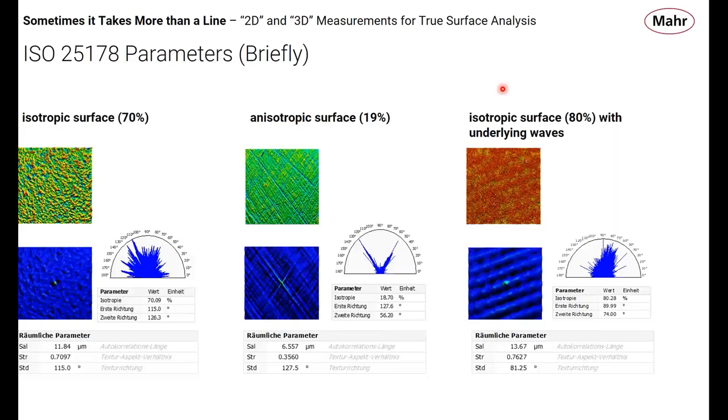And the reason I say that is, first of all, our isotropy is very, very high, but the two things that key me in there are our texture aspect ratio, which is actually quite high. It's higher than the surface over here that I called the isotropic surface, meaning that the isotropy signal is even lower. So the waviness isn't really having much effect on the isotropy at all. It's a very, very even signal, the directional signals.